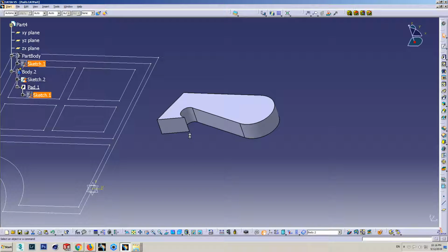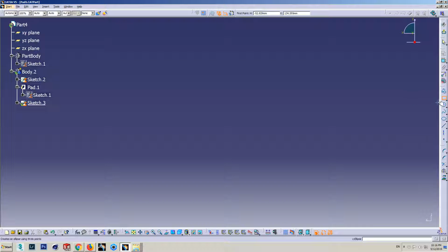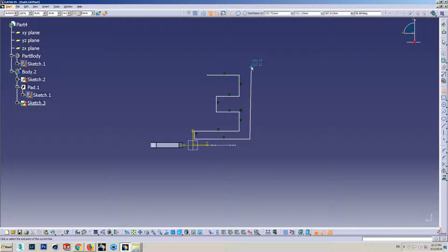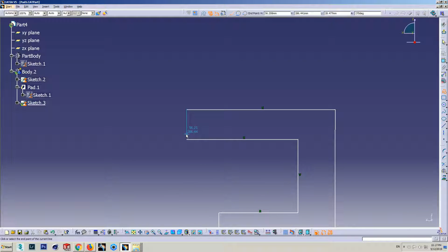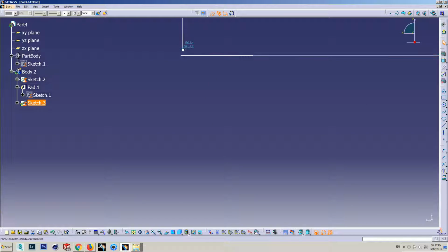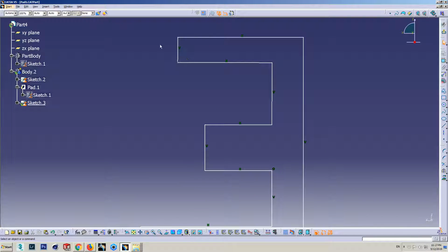For this, I will select this plane, Z and X. I will define a profile. Let's zoom out a bit, something like this. I want the up to next and up to last function to highlight those. I'm really not going to get into constraining or try to make this sketch, but I will make it a little bit not fully closed, like this. So let's see, I left there a little gap.